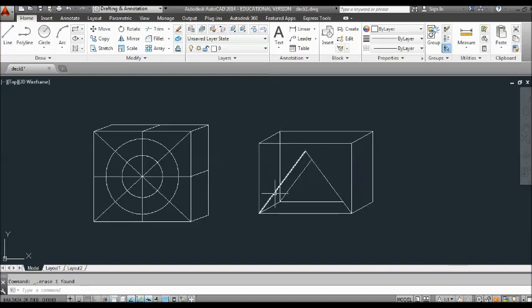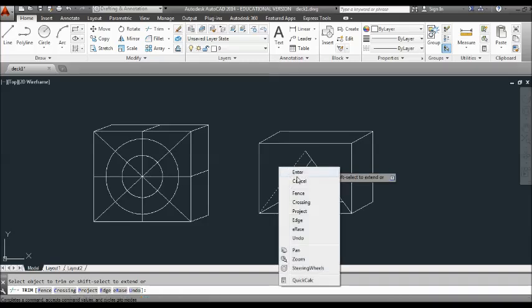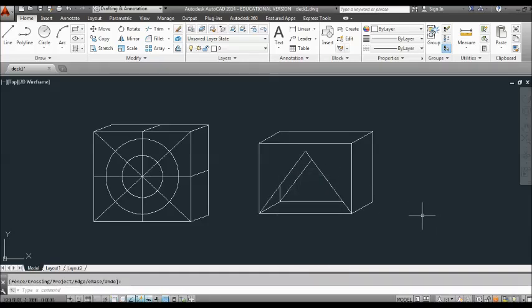Now back here you can also see we have a line here, and you'll be able to see through the opening here but not up above. So we got a new trim line, which is this one right here, and we're going to hit enter or right click on our mouse and select the line we want to trim. And there you go. The trim is all complete on this one here. It's now a solid object. You can't see all the lines inside the box, but you can see right through the middle there.